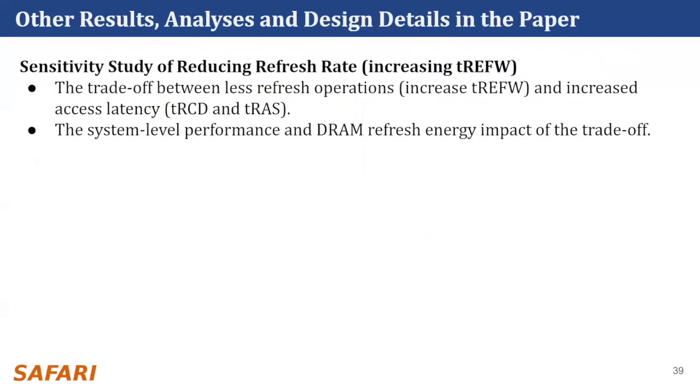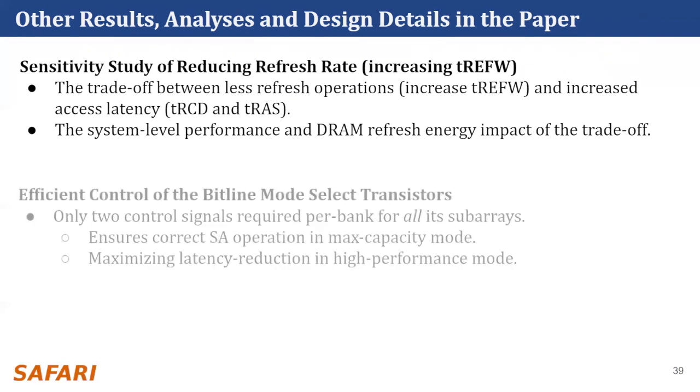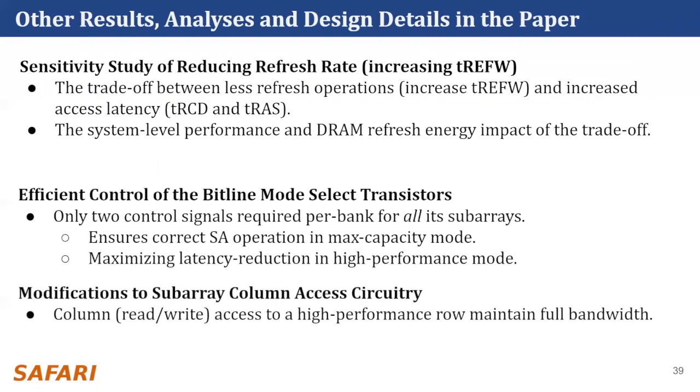We also have a more detailed sensitivity analysis on the trade-off between reducing refresh rate and the increased activation and restoration latencies, as well as the system-level impact of such trade-off, in our paper. Our paper also includes some design details that make CLR-DRAM work efficiently.